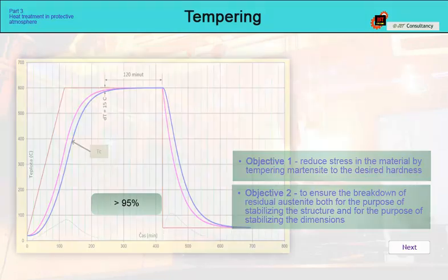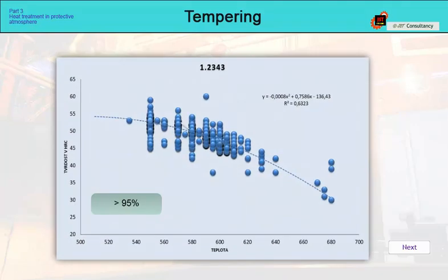On the other hand, systematically fixing the tempering parameters in the furnace program allows for subsequent statistical evaluation of hardness results and establishing your own tempering curves, valid only for a given furnace and for a given delta T parameter. If the heat treater adopts this method of tempering, then the probability of achieving the required hardness, regardless of the size of the part, is greater than 95%.